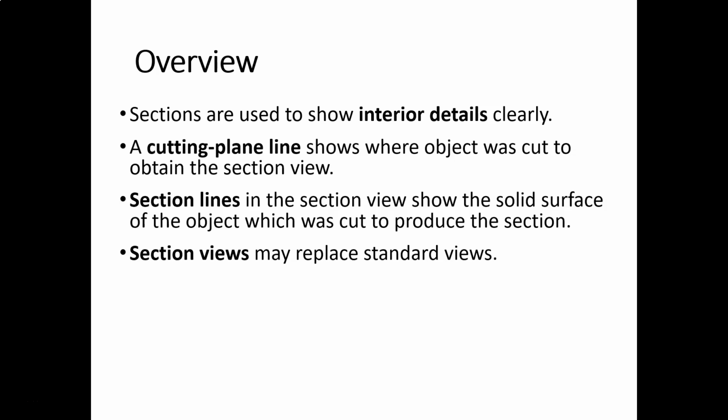Section views, obviously, may be used to replace standard orthographic views, your top, front, right side, left, bottom, back view, all those views. We generally want to omit hidden lines in section views. There are some exceptions to this rule, but generally speaking, 99% of the time, and hint, hint, in the homework assignments that you're going to be working on, you want to omit the hidden lines in the section views.